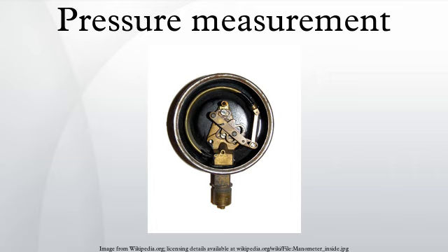Ionization gauge. Ionization gauges are the most sensitive gauges for very low pressures. They sense pressure indirectly by measuring the electrical ions produced when the gas is bombarded with electrons. Fewer ions will be produced by lower density gases. The calibration of an ion gauge is unstable and dependent on the nature of the gases being measured, which is not always known. They can be calibrated against a McLeod gauge, which is much more stable and independent of gas chemistry.